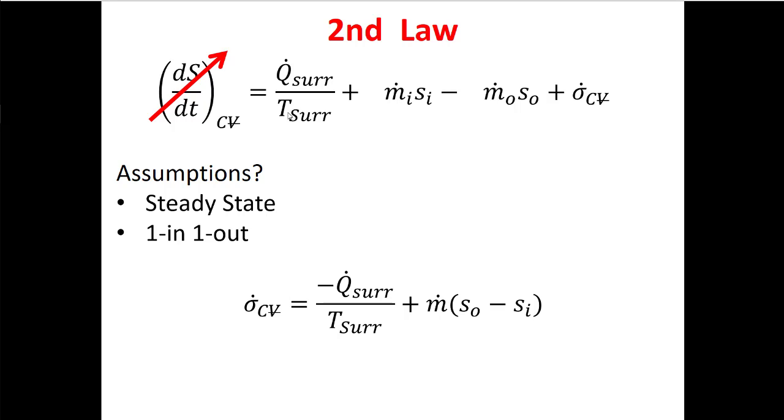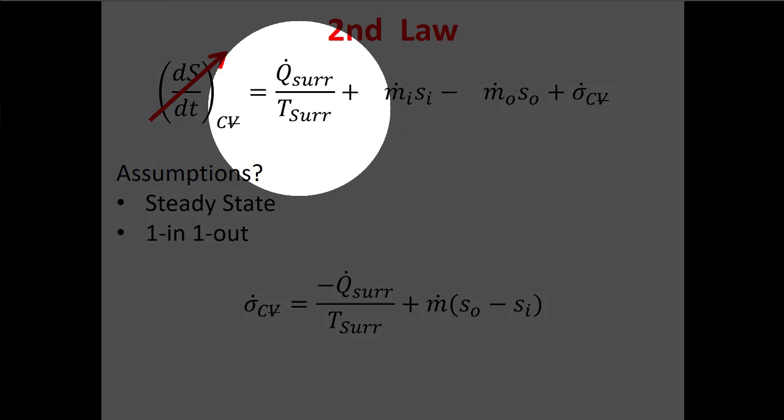We know that the entropy of our fluid is decreasing, but it's doing that because it's losing heat. So the rest of the system is gaining heat. If there's a bunch of air around our heat exchanger here, it's being heated up, and we know that as that thing is heating up, it's gaining entropy. So this is really telling us what's going on in the rest of the system.